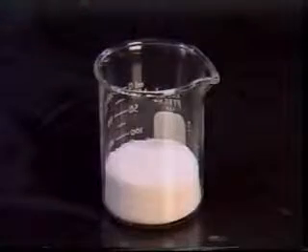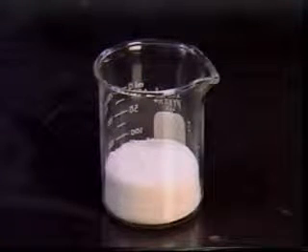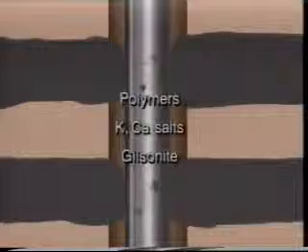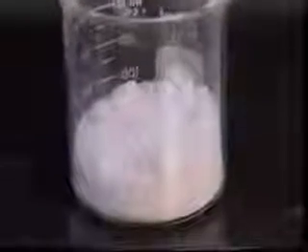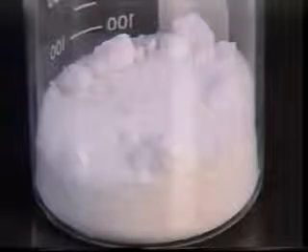Shale stabilization materials tend to inhibit the hydration of water-sensitive clays encountered in subsurface formation. If allowed to hydrate, these clays can heave or slough into the borehole, sticking the pipe or causing unwanted viscosity problems. Depending on the nature of the shale, a variety of additives may be recommended, including polymers, potassium and calcium salts, and gilsonite. Oxygen is always present in the drilling fluid, and only a few parts per million is sufficient to cause corrosion. Chemical oxygen scavengers may be coupled with reduced entrainment procedures to reduce the problem.